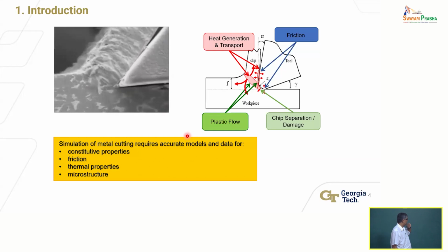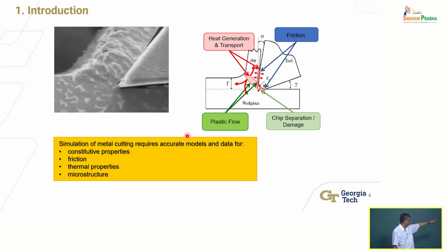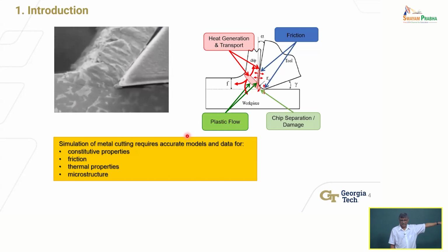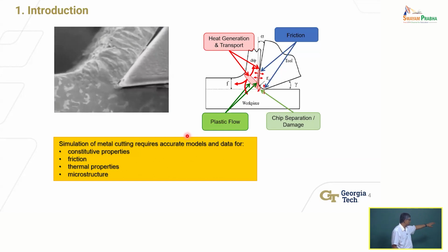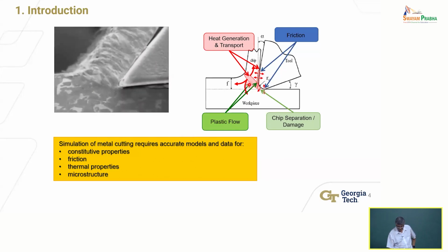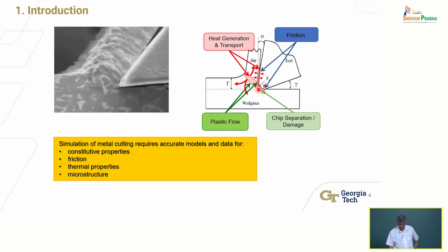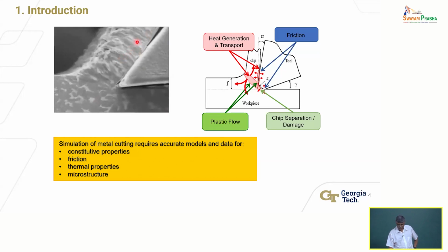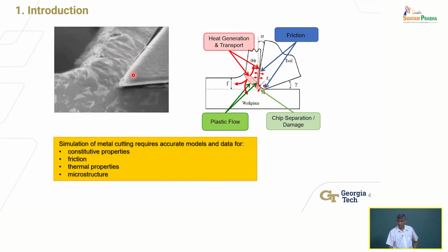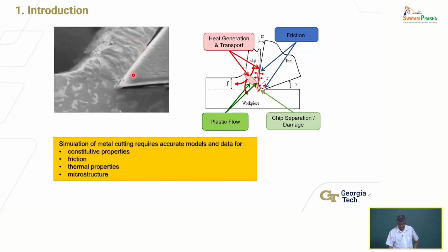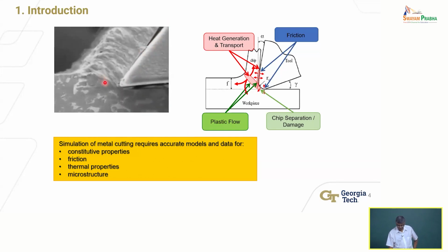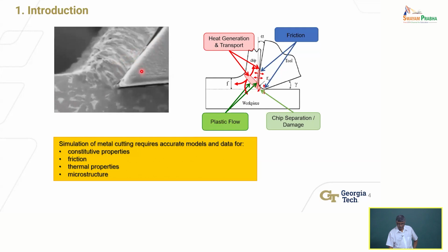Heavily sheared, which is denoted, there's an approximation of what is happening in the video that is shown in that sketch on the right-hand side, which shows you a pink-colored zone here, that is the region where much of the shearing is taking place, right? And then a chip forms, and it's flowing up. And notice here, the contact between the tool and the chip is quite intimate. It's very intimate, okay? Extremely intimate before it curls away and there is separation, right? So obviously there is relative motion between the chip and the tool.